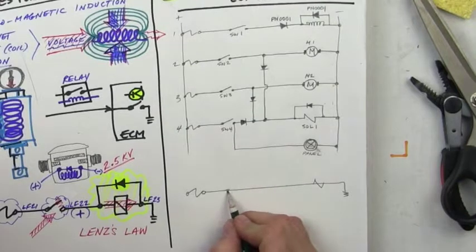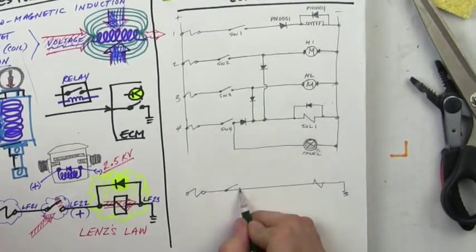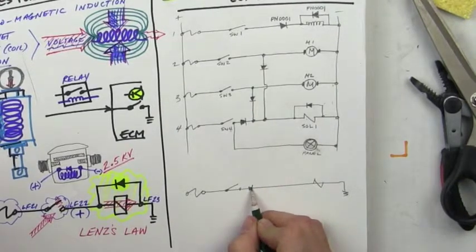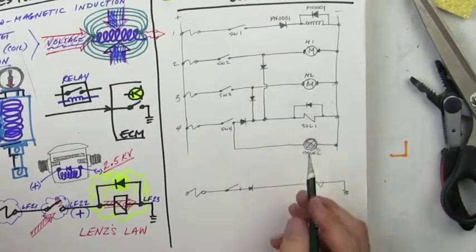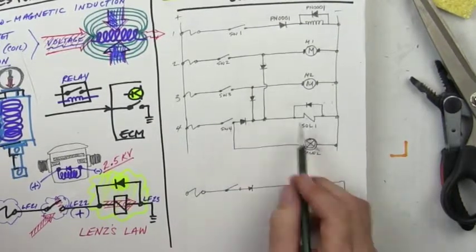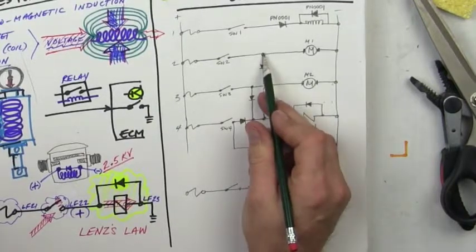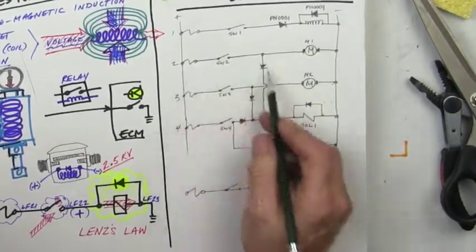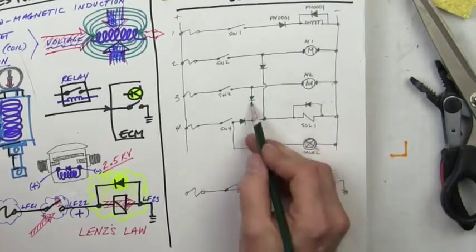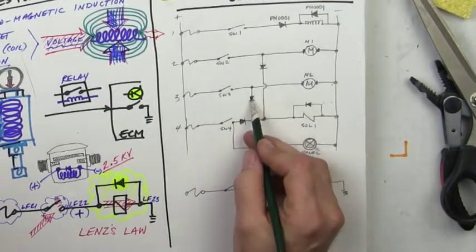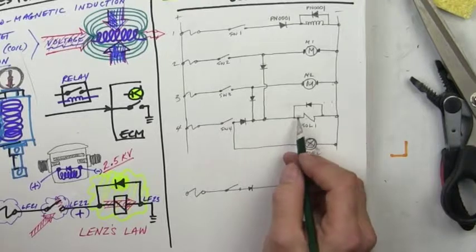And then I have a switch up here. And then I have a diode pointing in this direction, which matters. But it doesn't go anywhere else, so I'm reading this way. So current wouldn't go up this way looking for positive because I'd be blocked. And I wouldn't go up this way looking for positive because I'd be blocked, because the arrow is going against me.